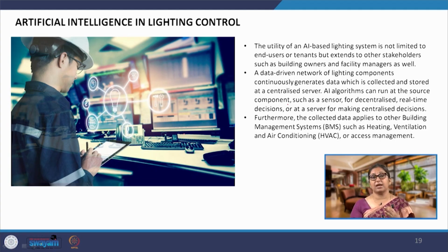All of this, natural ventilation, mechanical systems of ventilation and air conditioning, and the artificial lighting, can be put together in systems known as building information management systems, or building management system, BMS. There, taking the input from one, we can control several systems, and that is how smart buildings and energy efficient buildings are functioning these days.